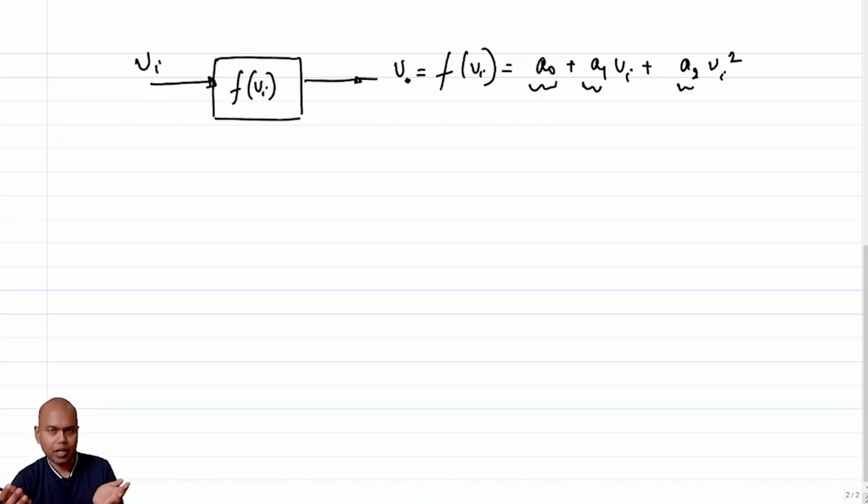A case in point is a transistor which is modeled as a square law, right? Having said that, we understand that no real transistor is a square law model. The models are highly complicated, and you can have all orders of harmonics or all orders of Taylor series, right? But for the sake of this discussion at present, we are limiting ourselves to second order.